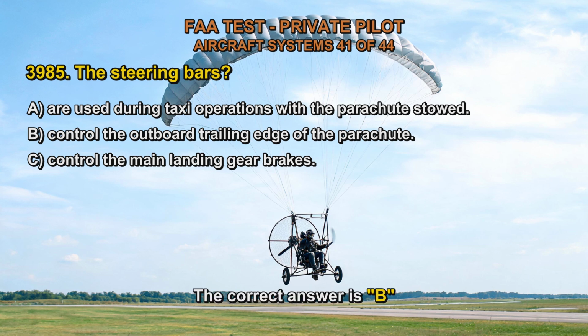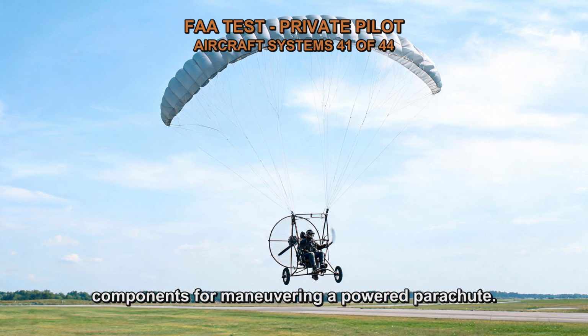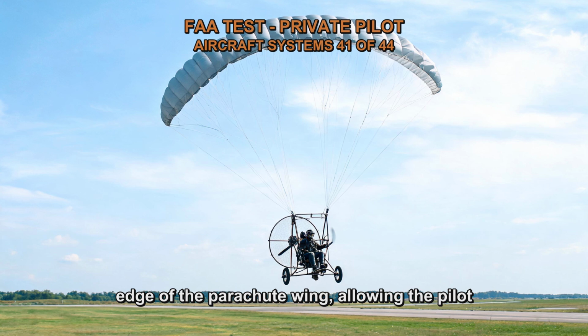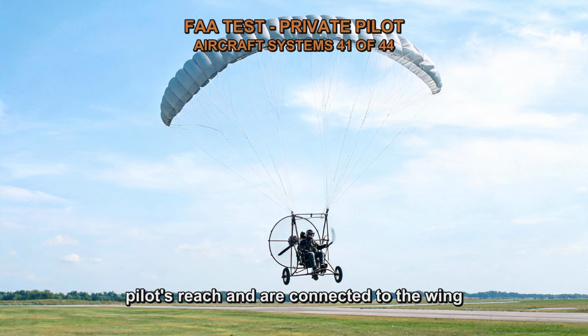The correct answer is B. The steering bars, or control bars, are essential components for maneuvering a powered parachute. They provide direct control over the outboard trailing edge of the parachute wing, allowing the pilot to navigate the aircraft effectively. The steering bars are typically located within the pilot's reach and are connected to the wing through control lines or risers.